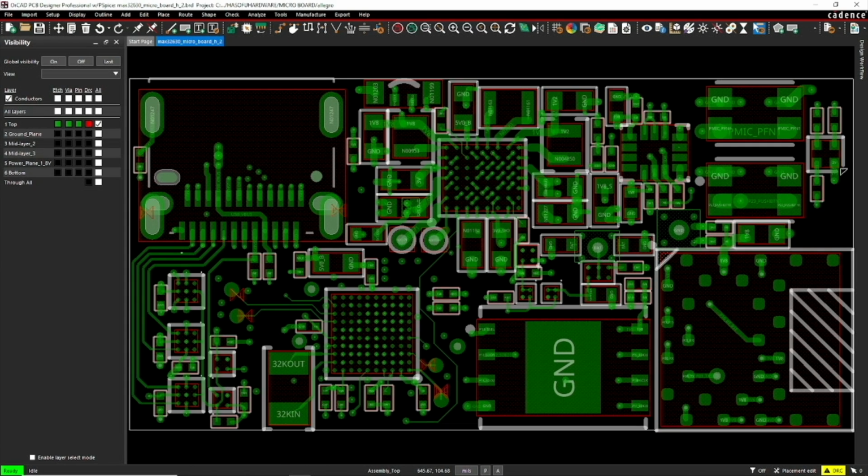The second occasion is when a trace needs to have a certain impedance. Otherwise, if you're not dealing with those two situations, feel free to take advantage of any available space to lower your conductor impedance. However, remember the trade-off of getting as many routing or signal traces as you can into any area of the PCB. So it's really a lot of trade-offs when it comes to routing and trace width.